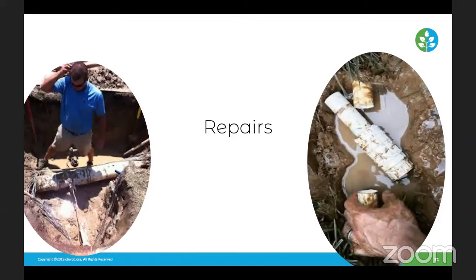So if that bleeder screw is leaking, the external bleed screw, and I think that's what we're talking about, I would even go and just try to turn it maybe an eighth of a turn, a quarter of a turn tighter to see if it'll stop. Because if that is leaking constantly, there's a possibility that the valve is not closing either.